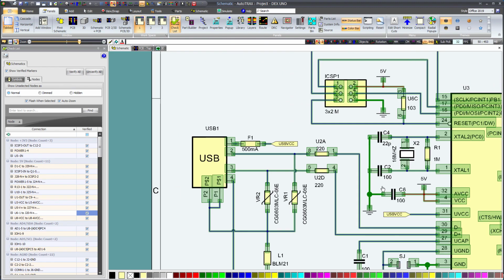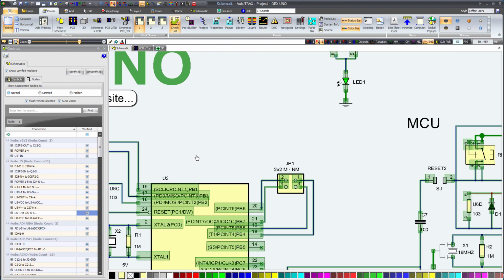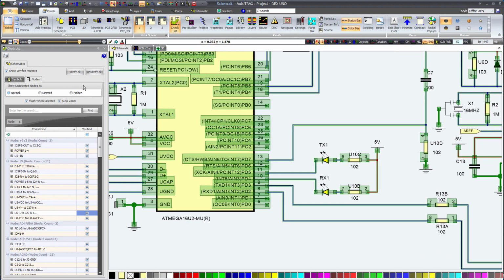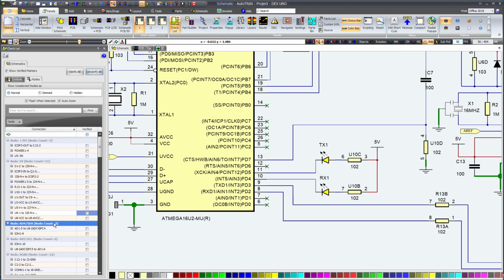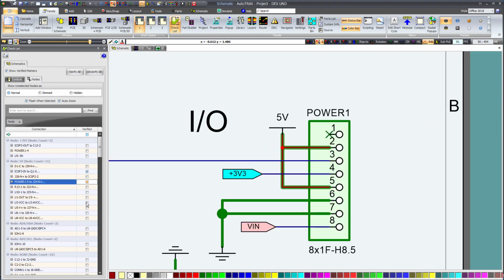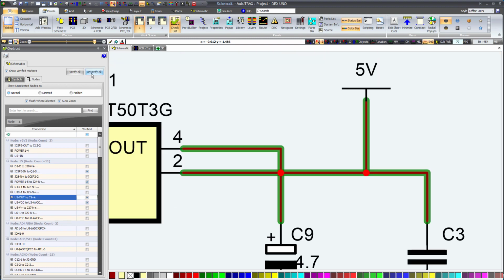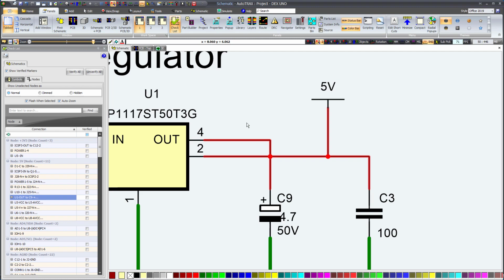The checklist panel works by allowing you to place semi-transparent marker pen lines over symbol terminals that have been verified, and over electrical schematic nodes that have been verified. This emulates the good old way of printing out the schematic, taking out a marker pen, and going around the schematic marking off checked circuit elements.